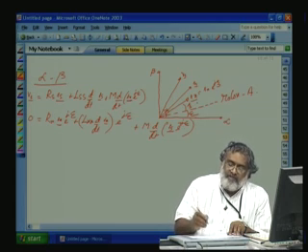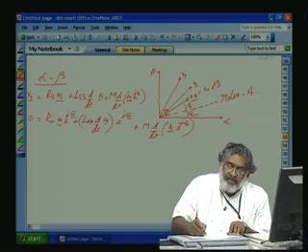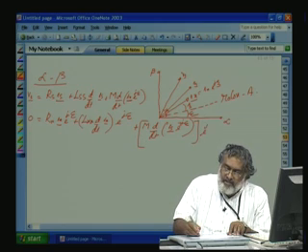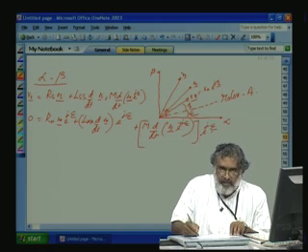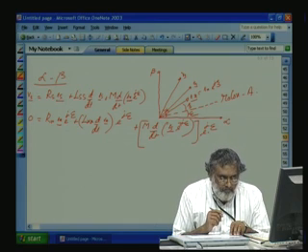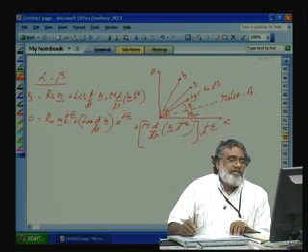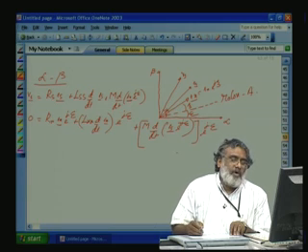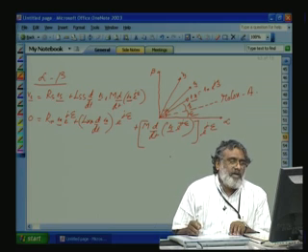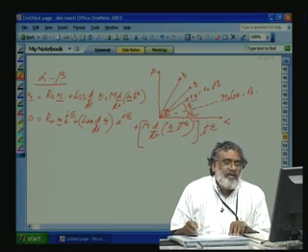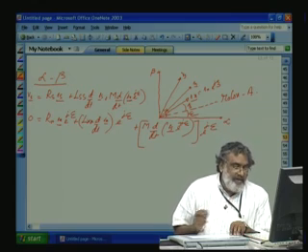So this is defined with respect to the rotor axis. Now everything we have to define with respect to the stator axis, so it will be e raised to j epsilon. This e raised to j epsilon brings the original rotor voltage equations, defined with respect to the rotor axis, to the stator axis.